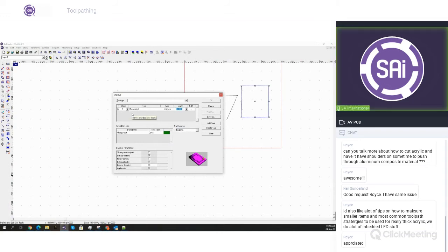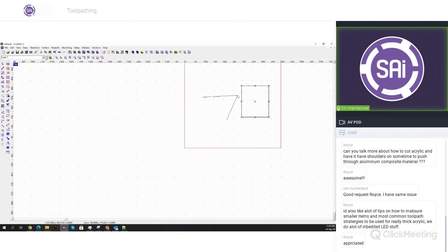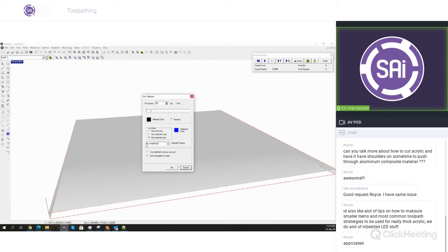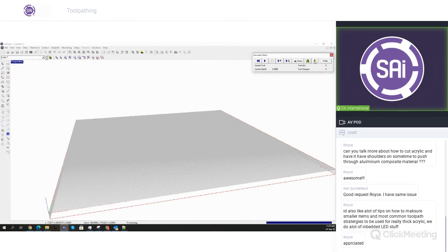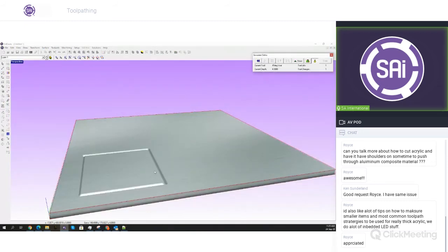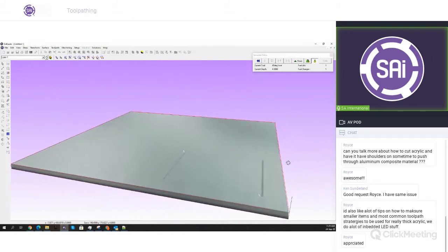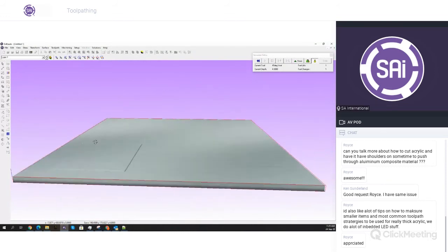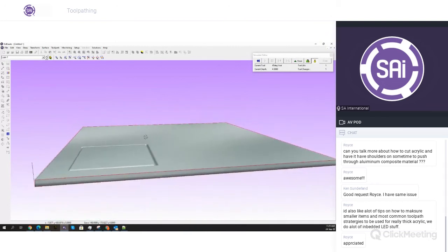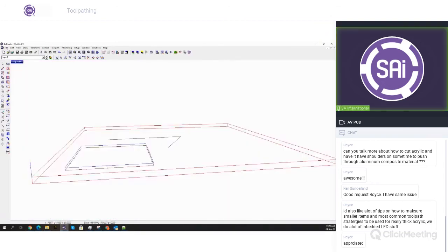So you can just set an engrave depth, for example, here, and it will simply engrave this line to that depth. But you also have the possibility, so let me just preview this. Here it'll just do that V-shaped cut over the contour that we've designed.